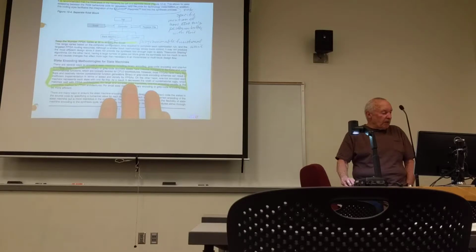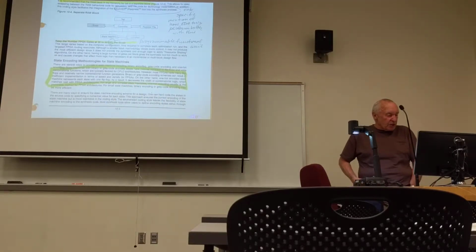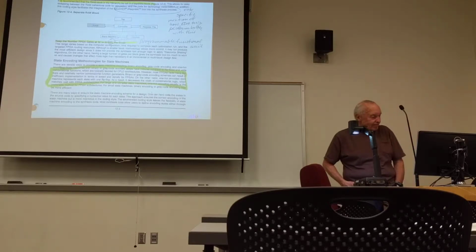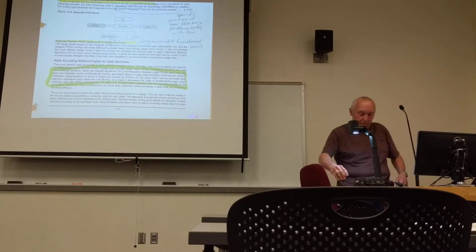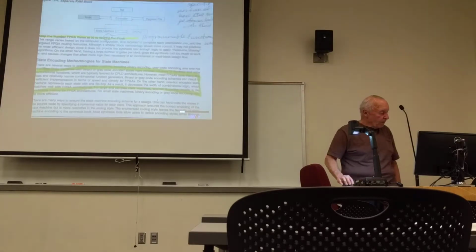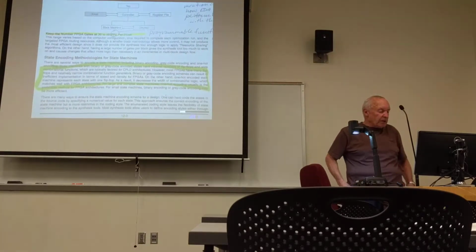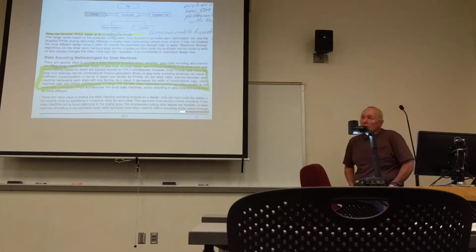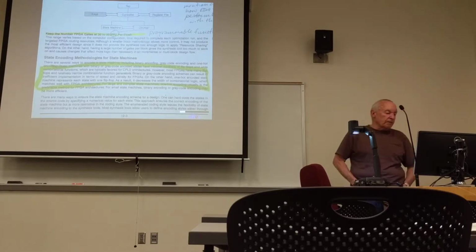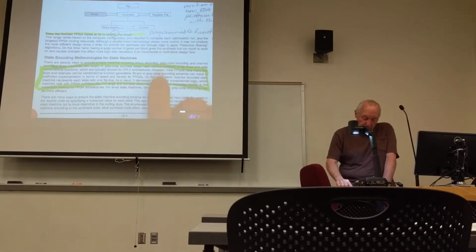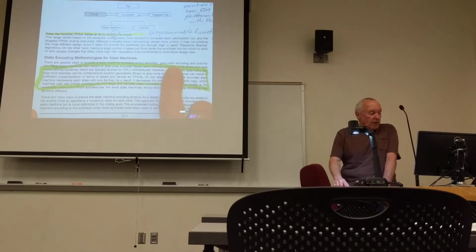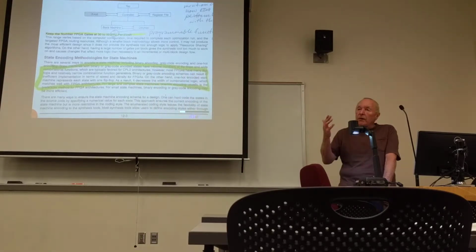State encoding methodologies for finite state machines. Okay, so you're going to have to pick some encoding of the states for your finite state machine. And they list some binary coding, gray coding, one-hot encoding, so you have different options available to you.